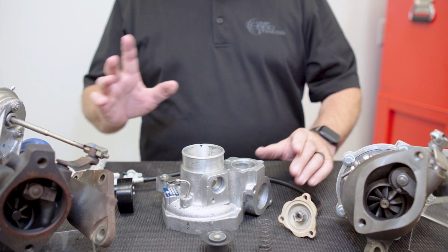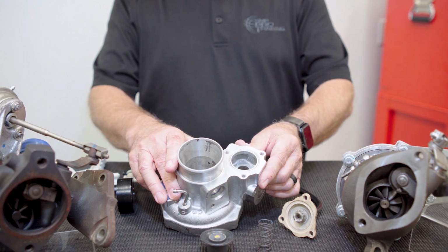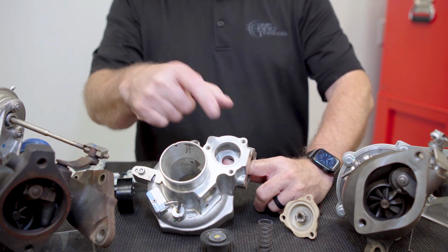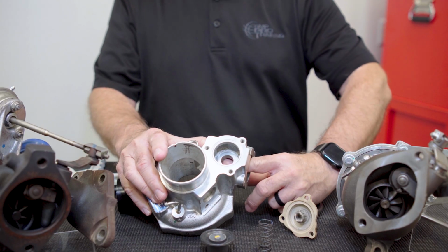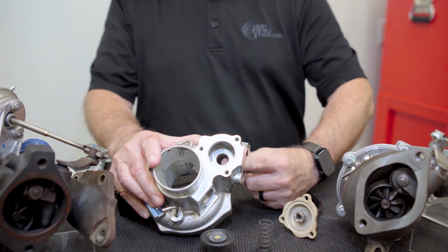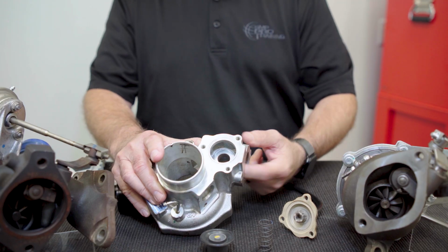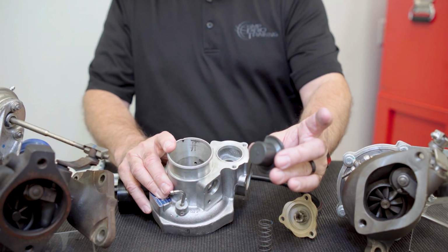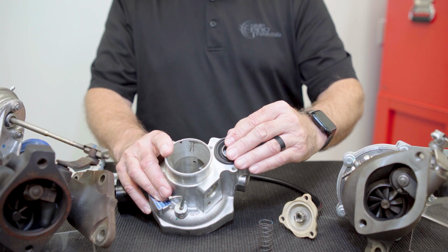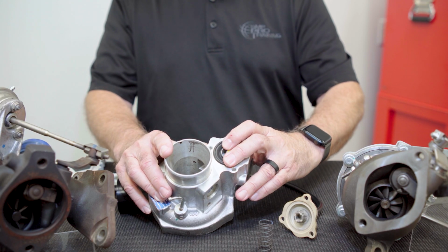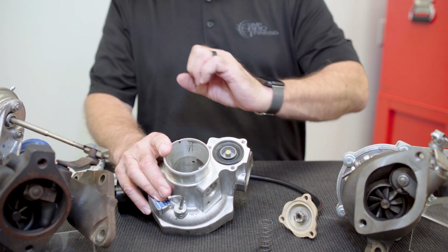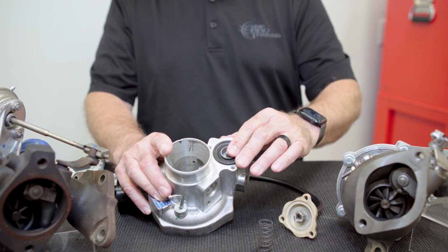All right, Corey. So here's what he's talking about with the bypass valve. And as you can see, there's a port, and you can see the port where my finger is pointing. So pressure comes in, and pressure with nothing against the port will go through this port. This diaphragm is supposed to sit and seat against that port, blocking the valve when we want pressure, when we don't have a situation where the throttle closes and we've got to dump all that pressure very quickly.